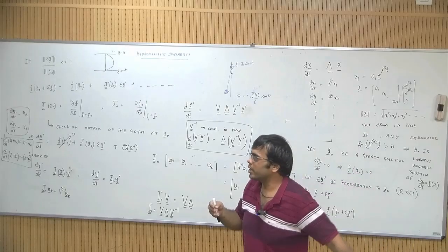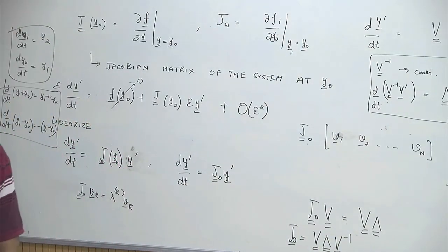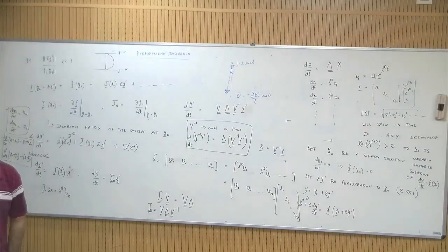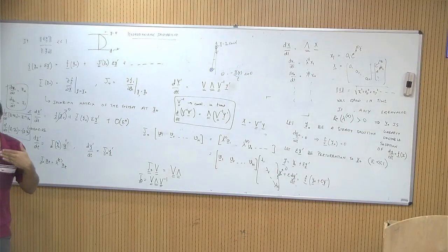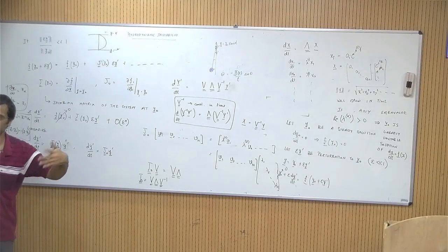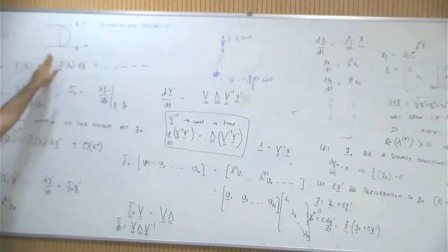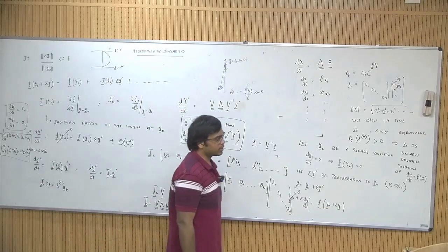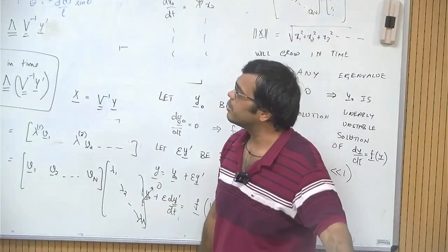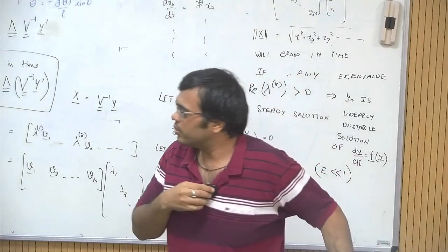Okay, so what it would mean is, for example, in this particular case, we will see there is a critical Reynolds number after which you have an unstable solution. This is an unstable solution after a critical Reynolds number. So physically what it means is that through a channel, you cannot keep a laminar parabolic flow profile after this critical Reynolds number. There will be some other type of a solution which will break the assumptions that you have made when you try to derive this. Okay, so that is the essence of hydrodynamic stability. Next class we will start looking at how to apply all of this in fluid dynamic equations.